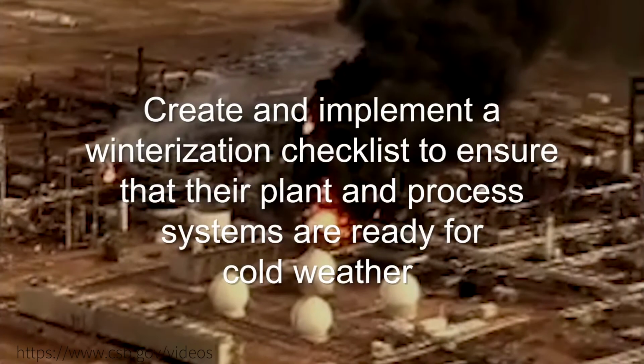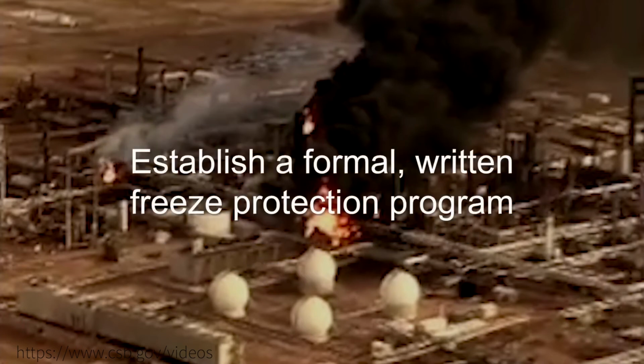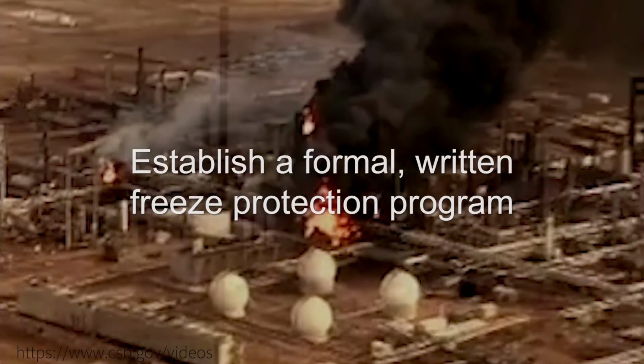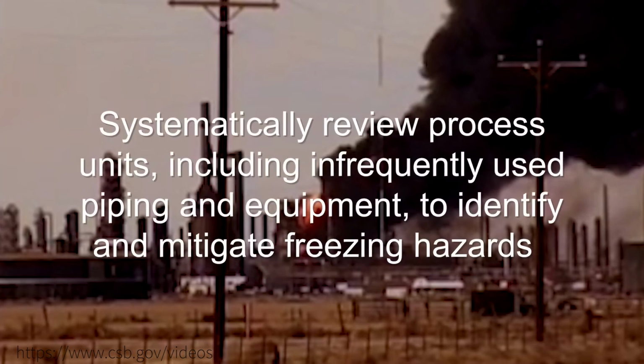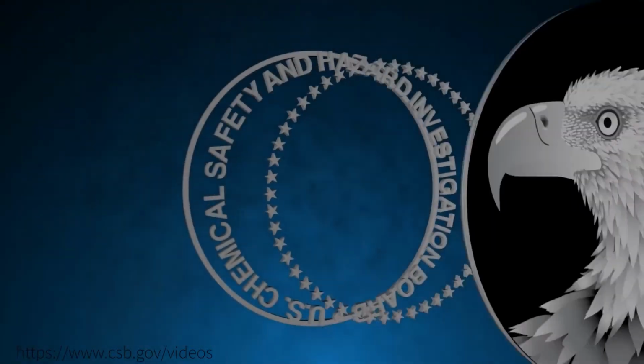Create and implement a winterization checklist to ensure that their plant and process systems are ready for cold weather. Establish a formal written freeze protection program. Survey piping systems for dead legs and ensure they are properly isolated, removed, or winterized. And systematically review process units, including infrequently used piping and equipment, to identify and mitigate freezing hazards.